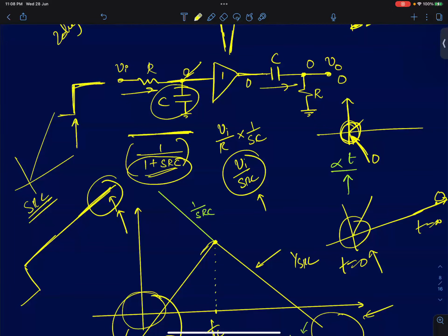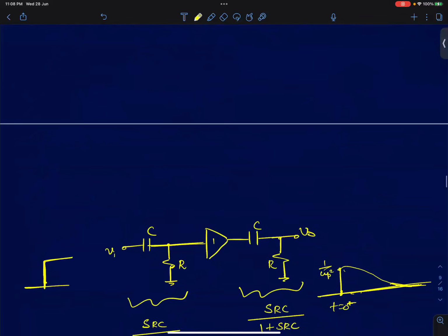But if the circuit is too complicated, or if you are given the frequency response, you can predict it as well. Okay, whatever suits you. Fine. So that's how we predict behavior of higher order systems by looking at the frequency response. I can say what the initial and the steady state responses are.